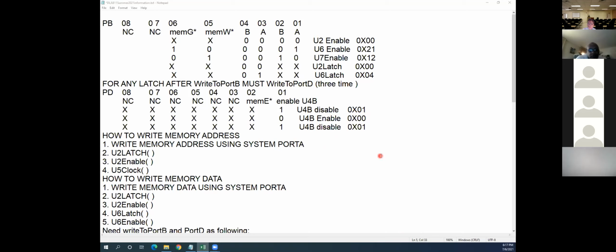That's the difference between the 373 being a latch, which is controlled by that pulse, and the 374, which is controlled by a clock transition. So you have your flip-flop versus a latch. The 374 is a D flip-flop, edge triggered. The 373 is a D latch, controlled by the high at the latch enable, not the clock.